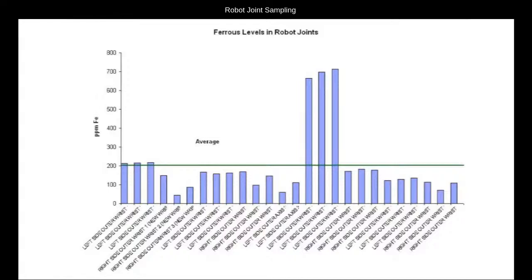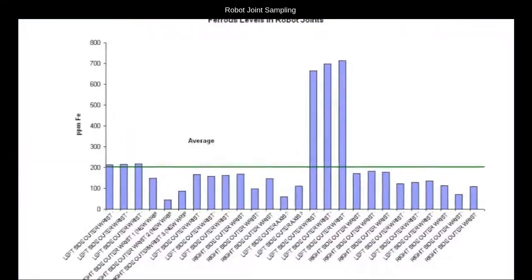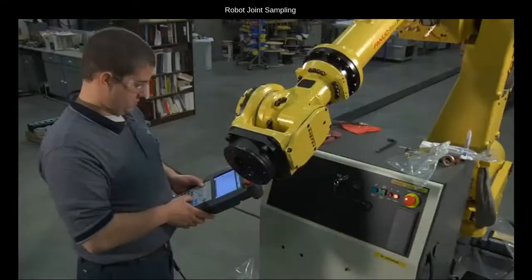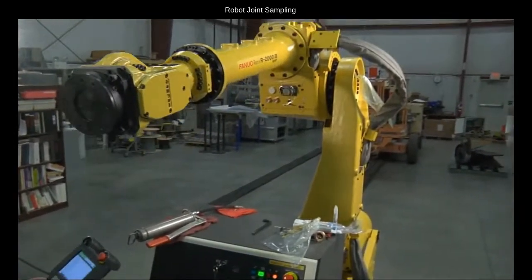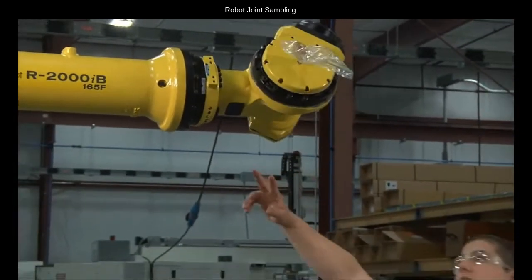This graph shows the kind of information available just by running a simple wear test on this set of 30 samples from FANUC Model 2000 harmonic drives. 3 outliers in this group are immediately apparent and provide a clear differentiation that will allow a prioritized strategy of inspection and maintenance that will minimize downtime and reduce the chance of unexpected failures.